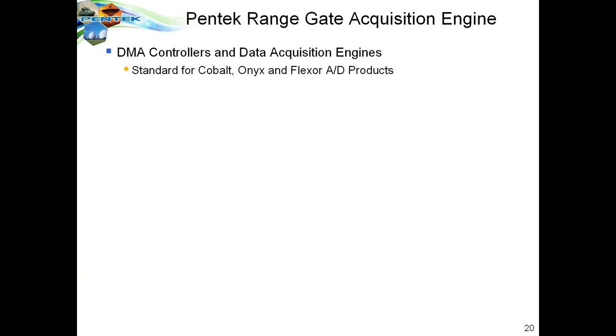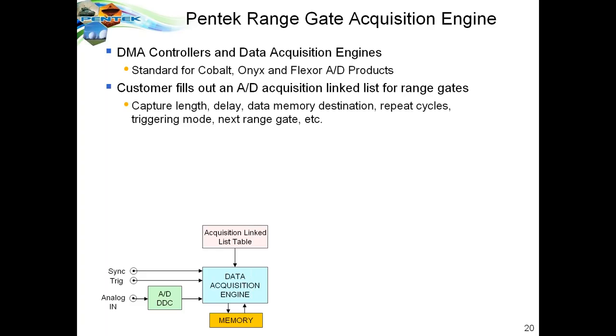Of course, the other side of radar is acquisition of the radar pulses. Pentek incorporates DMA controllers and data acquisition engines in all of its IP for Cobalt, Onyx, and Flexor A2D products. And we use a similar linked list for the AD acquisition, very similar to the linked list that we used for the generation in the previous slides. So we specify the capture length, the delay from trigger, the destination for memory, and then the number of times we might repeat, the triggering mode, and so forth.